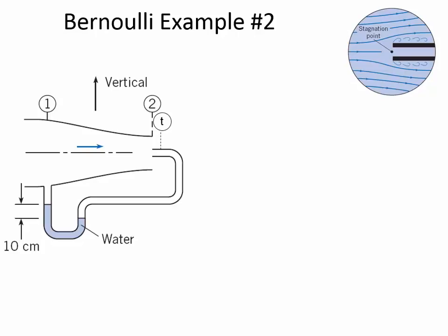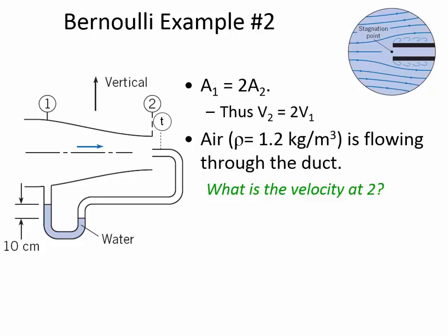And so inside this tube, there is no airflow in the tube. Conditions are static. But if you look at this deflection of water, what's causing the fact that the water level isn't the same is because there is stagnation that has converted some velocity into an increase in pressure. So it's not the fact that the velocity is higher at 2 that makes the pressure higher on this end of the manometer compared to that one. It's because of the stagnation effect that's happening.